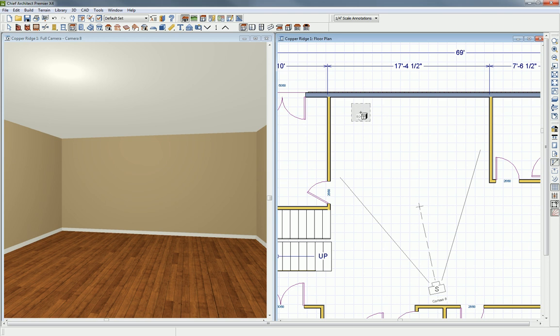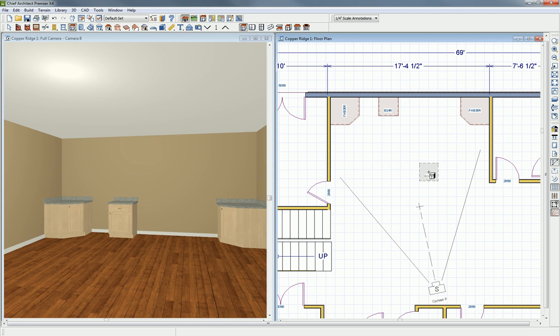of a given manufacturer. So when I'm doing a kitchen design, I typically like to get my corner cabinets in place. So if I pull this tool over and I bring it close to the corner, it recognizes that corner and it changes the cabinet over to a corner cabinet. So I'm just going to click down our two corners to get them in place. And then I'm just going to drop here in our wall another cabinet that I'm going to configure a little bit differently.